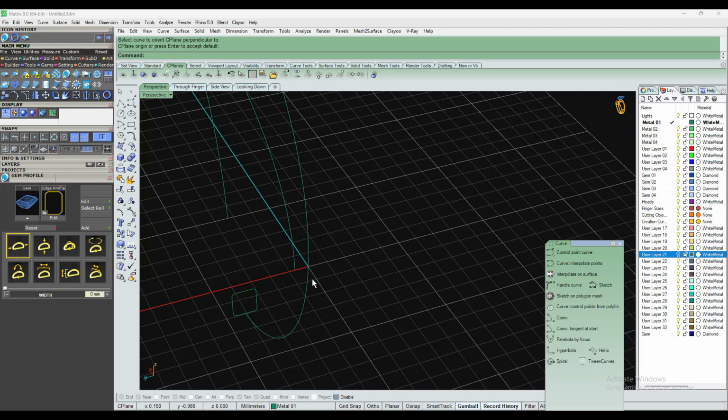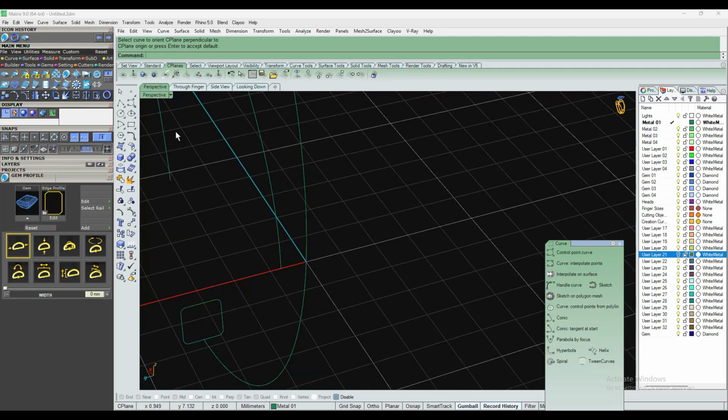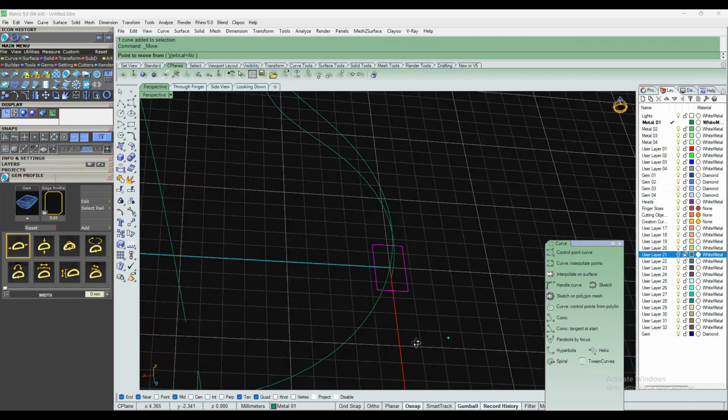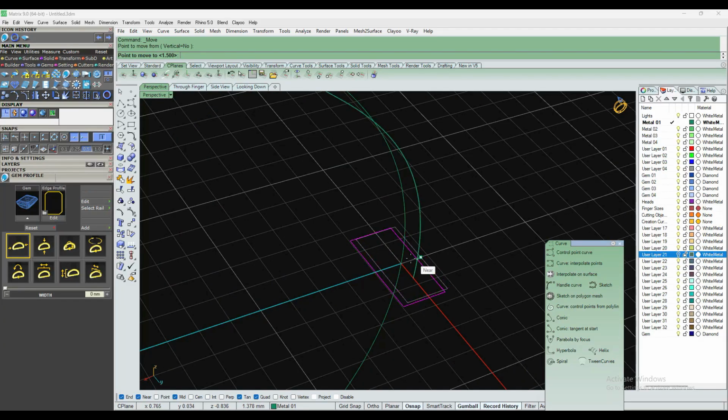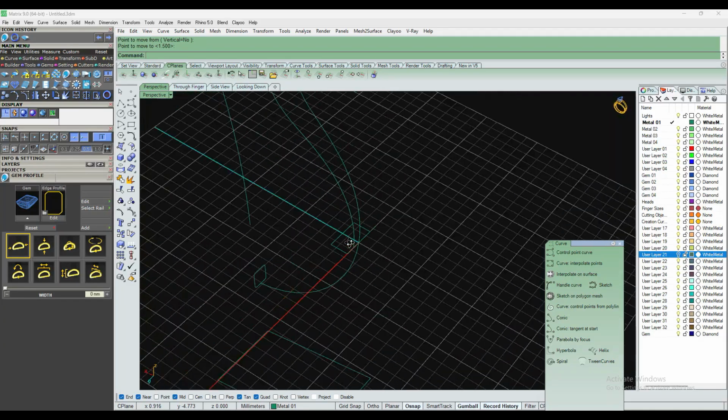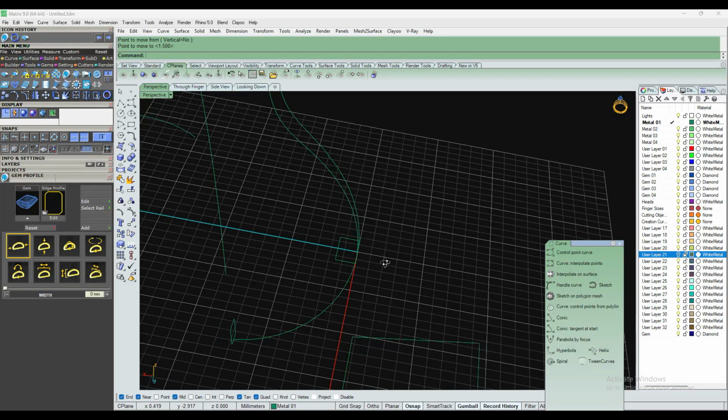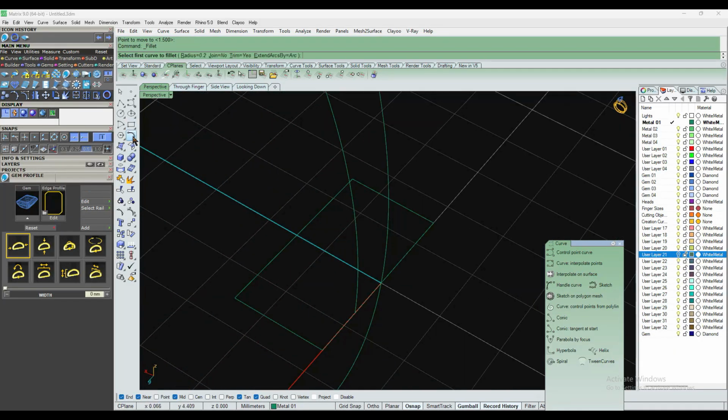I want to connect this profile to this profile, so I am going to use the center rectangle. Turn on O snap option, click here, and let's make it 3.1 by 1.5, and let's bring it to this inside portion. Okay, so our inside rail is passing through this point to this point. You can also add your fillet. So for now let's make it 0.2. This is fine.